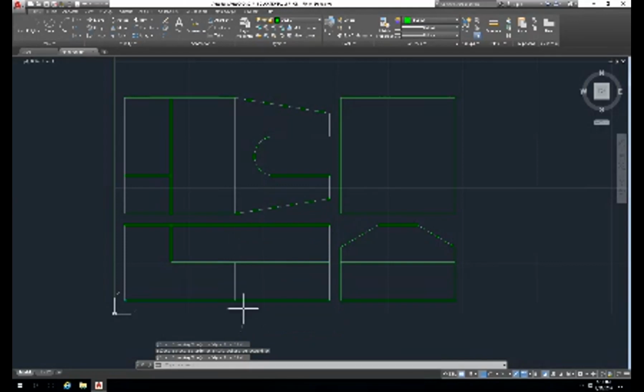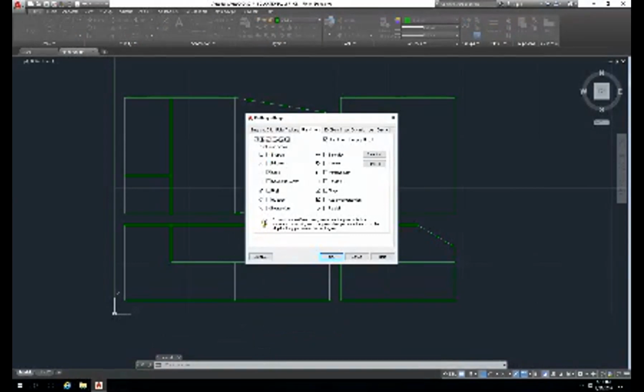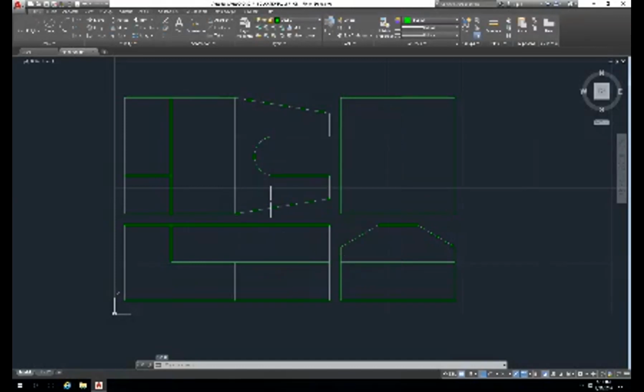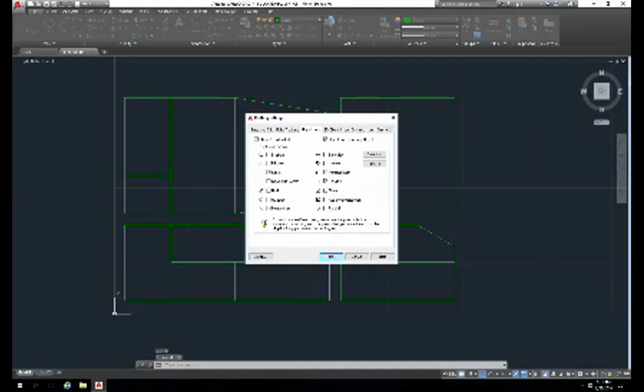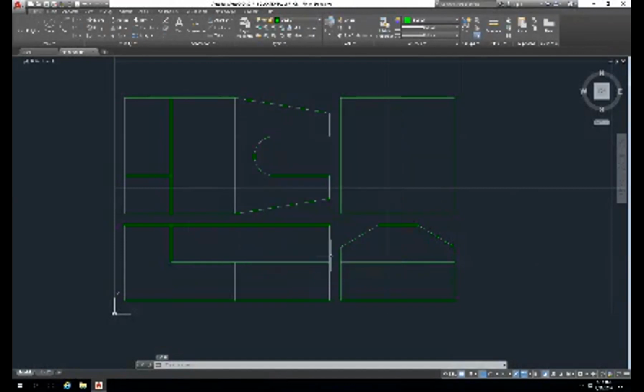now we have a hidden feature, and this right here, we need OSNAP. We need OSNAP that is going to give us, well, let's try tangent. It's going to give us tangent. And let's turn on perpendicular as well. Once again, that's what I was entering in. So when I was entering in INT, that is the same as intersection, and you see it tells you that it's displayed with an X.